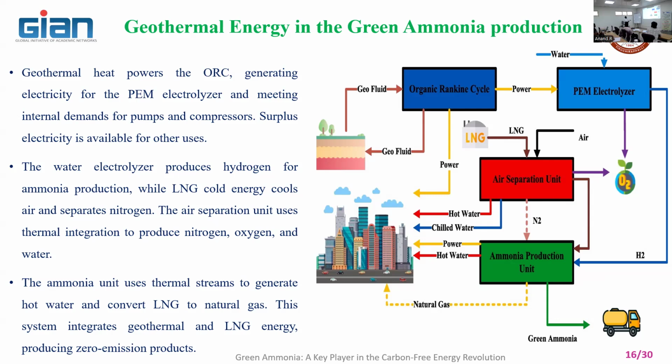In the same way, you put a drill under the earth and find the heat available at the molten lava at a particular point. You inject water at that point. When you inject water into the high temperature, high pressure zone underneath the earth, superheated steam will come out. That steam is utilized for power generation, like in a conventional steam power plant.